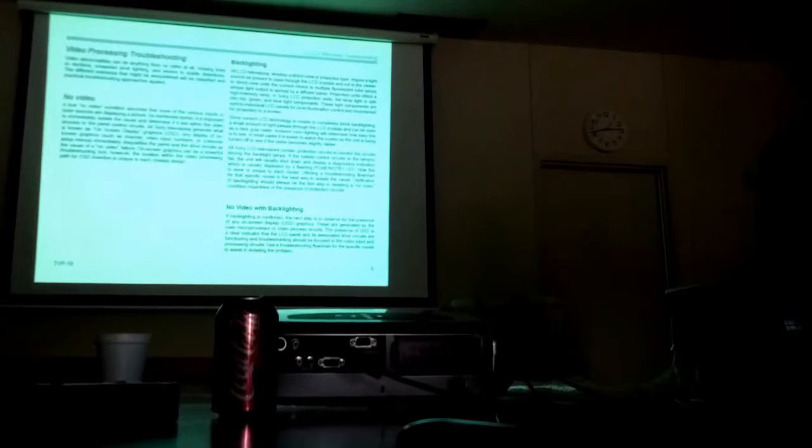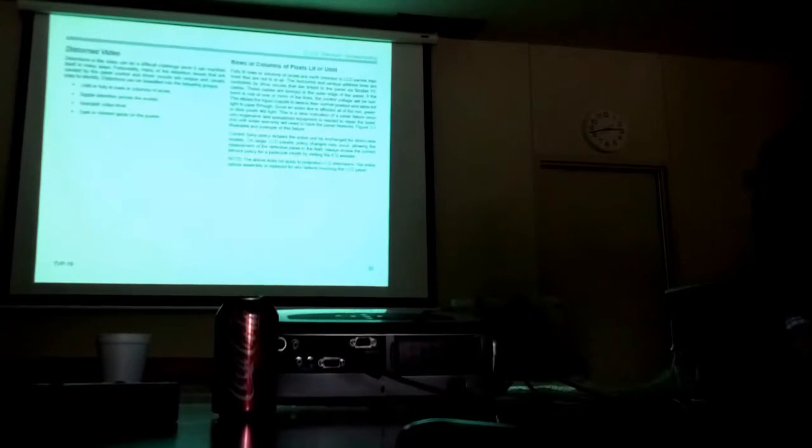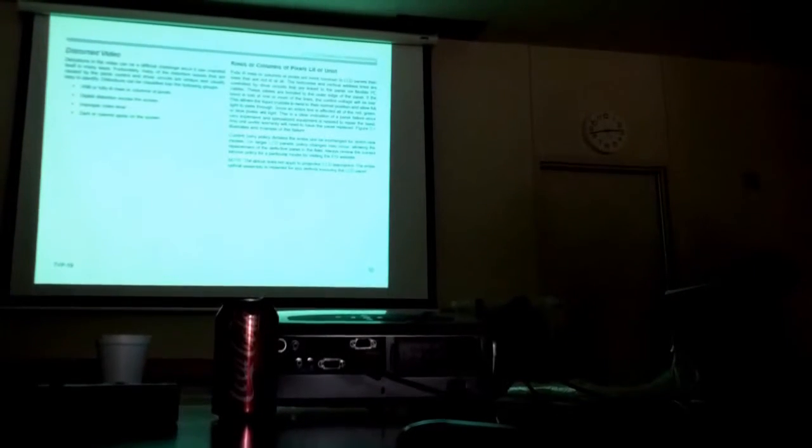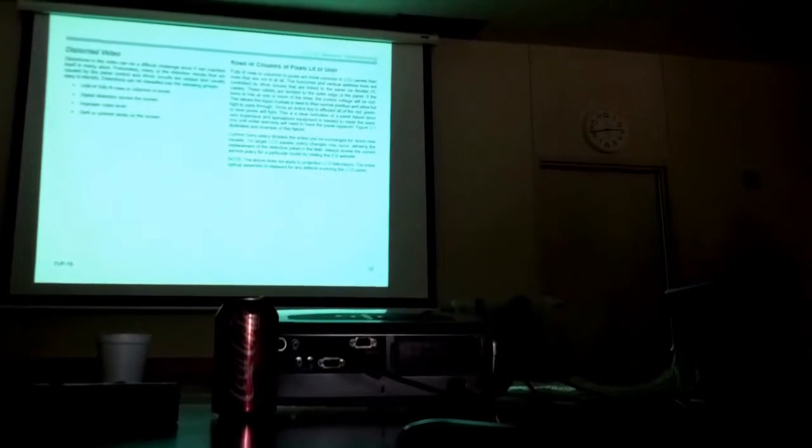So what if you have a problem with an LCD? Well, they fall into a couple of different categories. One is very uncommon, and that's distorted video. If you have distorted video, I'll almost guarantee you it is not your display.